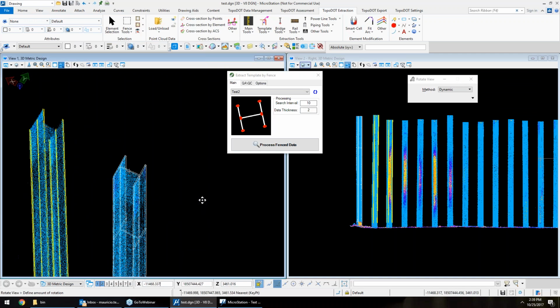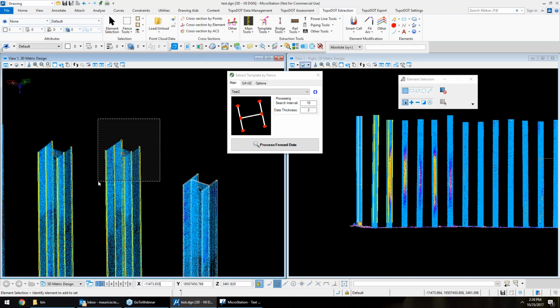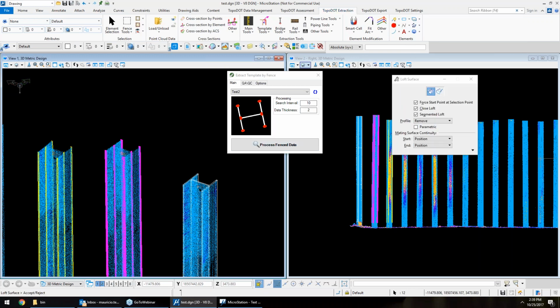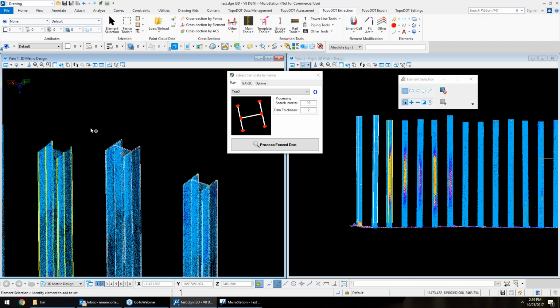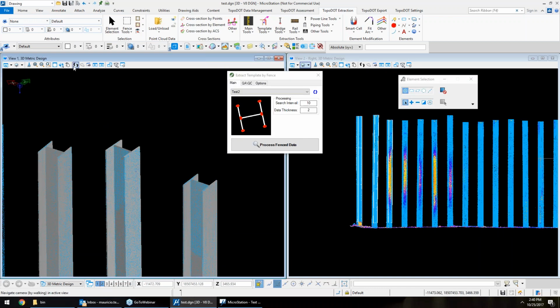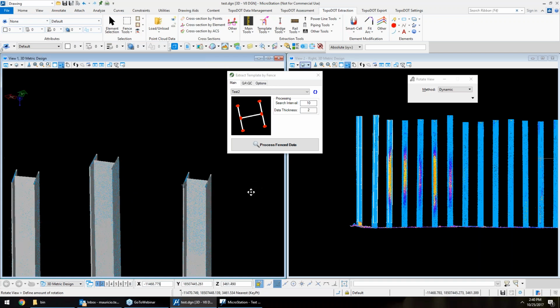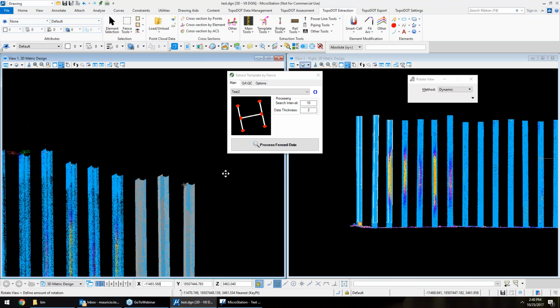And what Monty said, make your template. It's not your template. It's actually just those break lines, the red points, right? Yeah, that have to be in order. Right. So you can make the template any way you want. That's not a problem. And then when you apply the red points to break lines that you're extracting, make sure they go in an order that you'd want them to be attached to form those break lines to form a plane, to form a surface. Does that make sense to everyone? I hope. Any questions out there?